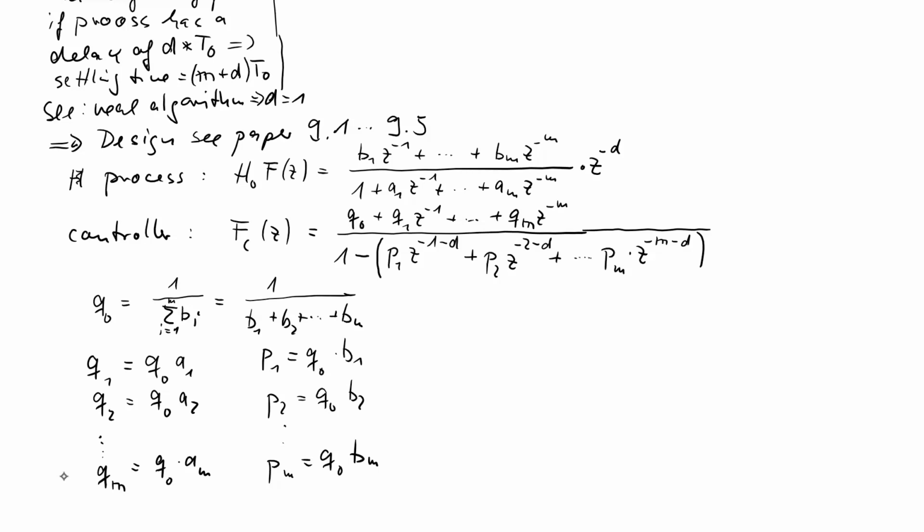And you see, we have also a possible adaptive controller, because an identification method can throw out the A's and B's, and with this equation set, you can easily calculate the new set of controller parameters. Just some multiplications. Yeah?